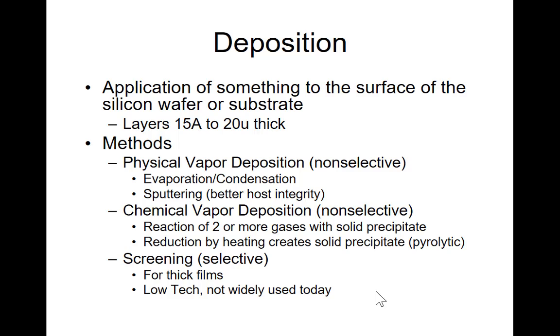And you have part of materials there. You are heating it up using whatever method, and then it bubbles, and then the materials come up and get sputtered onto the wafer surface. And in that process, you will spin your wafer and change it so that it gets a uniform layer of materials on the top.